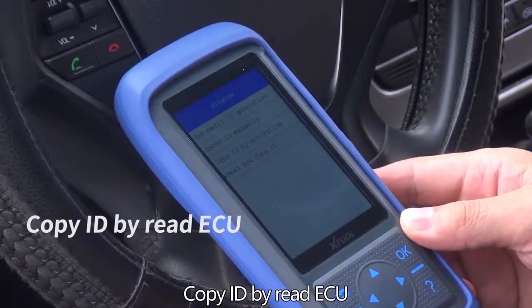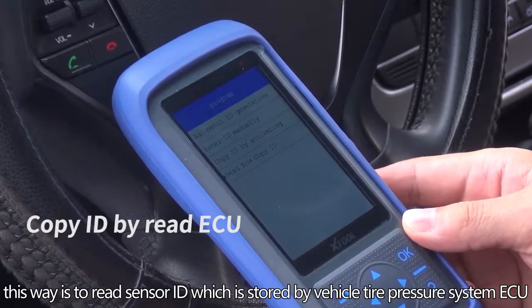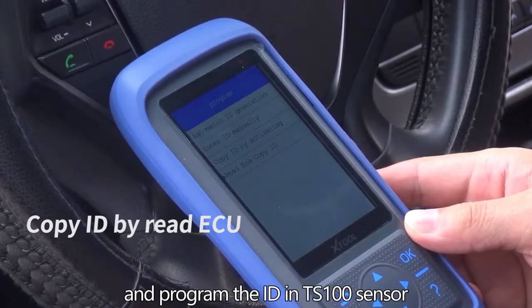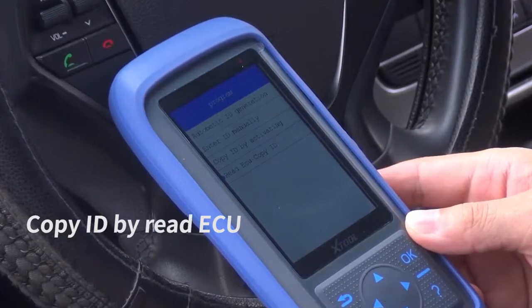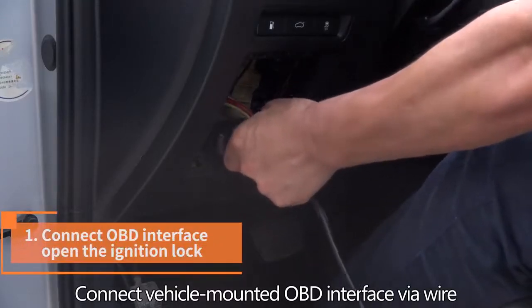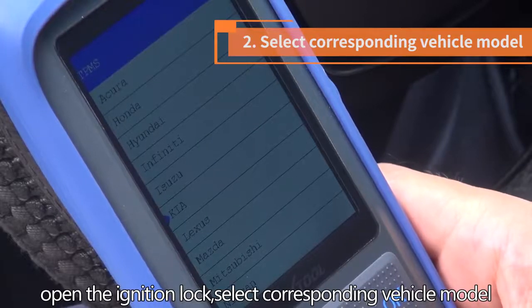Copy ID by read ECU. This way is to read sensor ID which is stored by vehicle tire pressure system ECU and program the ID in TS100 sensor. Connect vehicle mounted OBD interface via wire. Open the ignition lock. Select corresponding vehicle model.